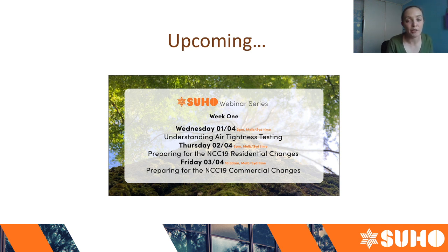The reason that we use permeability across the board in testing commercial and residential buildings is because they are comparable numbers. Because the volumes are so vastly different in residential compared to commercial, you could get a false outcome using the volume of a building because it is so large. So what we're really trying to test is the building envelope. We're testing what leaks out of the building envelope. That is why we use the area of the building envelope to quantify and normalize the airflow to get a result. So I don't know if that answers your question.